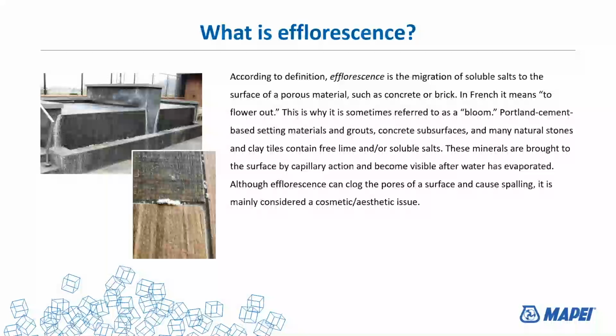Portland cement-based setting materials and grouts are usually one of the first problem areas because of the Portland cement, and many natural stones and clay contain free lime or soluble salts. When water is brought into the situation, the salts are brought to the surface by capillary action, and when the water evaporates, that's when you start to see the salts. They dry to a white salt.